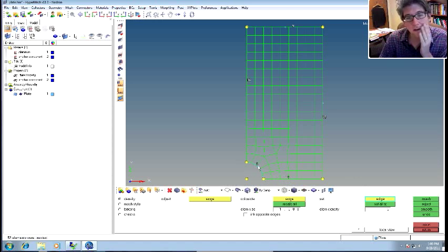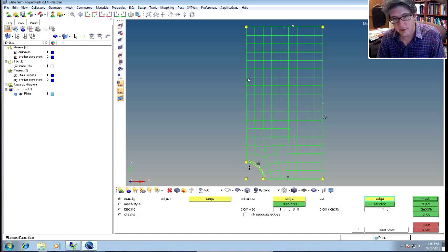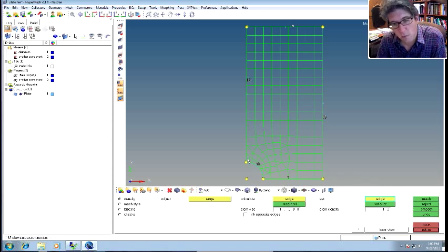So you can control things that way. That's actually kind of nice. Actually, maybe that isn't even enough. Let's make it like 10, and let's set that edge, so we'll click it to 10. You can see the mesh results from that. Now that's getting a little weird because it's really going to have a tough time getting fine mesh here and then getting out to the coarse mesh. So you can see my elements are starting to get very distorted.